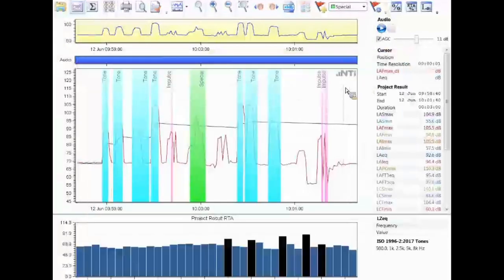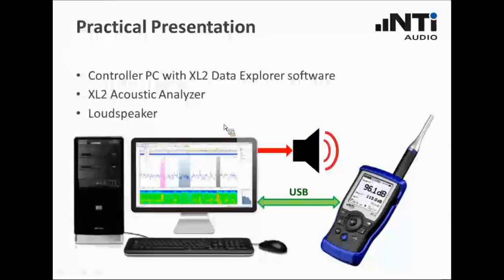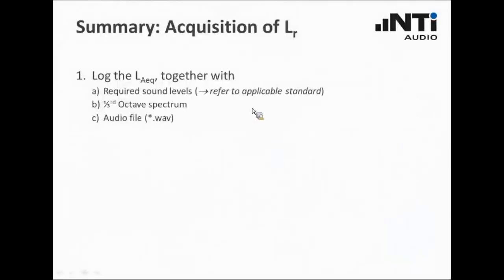Well, let me get back to my presentation and summarize the procedure. We start with the recording of the sound pressure level, the LAeq. In addition, we recommend to log all the sound levels that might be used for these post-processing calculations. We strongly recommend to, of course, log also the third octave spectra for the tone analysis and the audio file for the FFT analysis as an alternative.